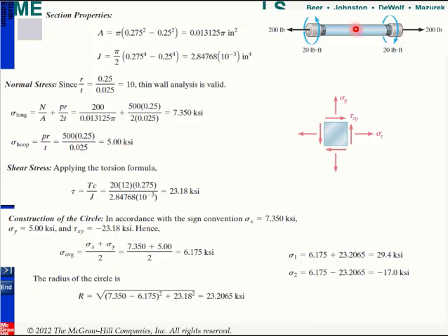Okay, and depending on how you cut it, you can determine your axes. Sigma x is longitudinal, and I will say that the other, perpendicular direction is sigma y, and this is our positive direction. And due to this torque applied counterclockwise, I will get a minus sign on my shear. Okay, and the rest is to find the average and R. If you add them, you will get your maximum. If you subtract them, you will get the minimum.